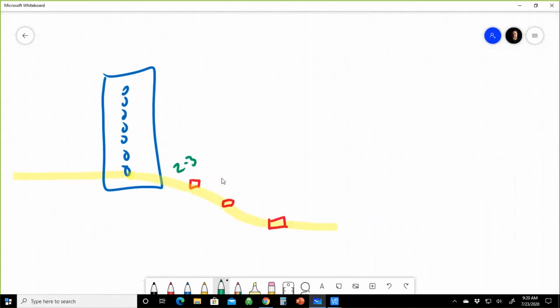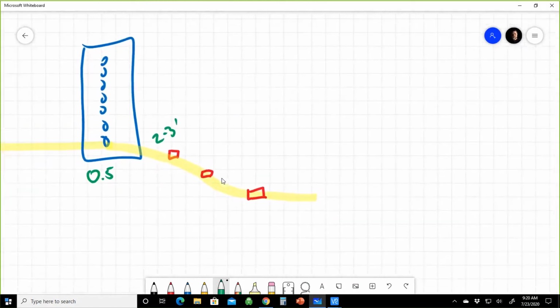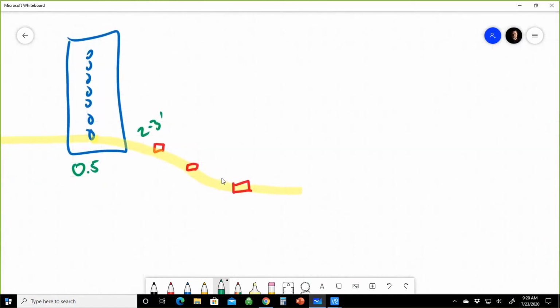So 2 to 3 feet. Usually it's too close, it merges into the connector. So we have 0.5 dB max from the connector itself, from the FTP panel. We're going to have 0.1 from the pigtail splice. And then another 30 feet away, we have a transitional splice, going from your inside cable to outside cable, that's going to be another 0.1.